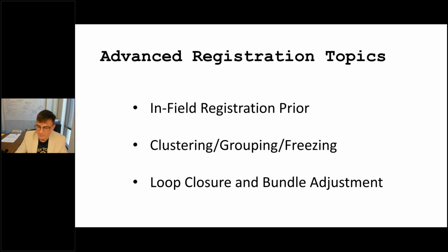I'll quickly throw in some more advanced concepts. In-field registration is a first pass registration done in the field. Clustering allows you to break the registration process down into manageable pieces. It gives you a little more control over how registration is done and how errors are distributed.